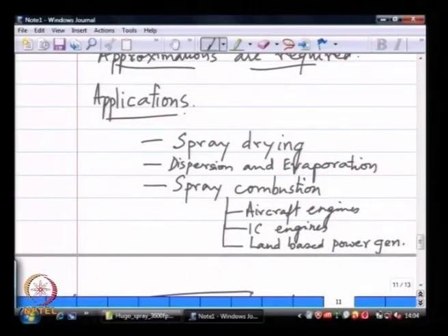So, again the conflicting requirements are that if I spray a perfume here, I want the far end of this room also to see some effect, or at least I do not want the effect to be completely localized in a small region right adjacent to the nozzle. So again I want some large drops that will remain in flight for a little while to give me this length and penetration to the spray, because I do not want to be walking around every nook and cranny of this room to be spraying. So, these are the different conflicting requirements as far as dispersion and evaporation is concerned.